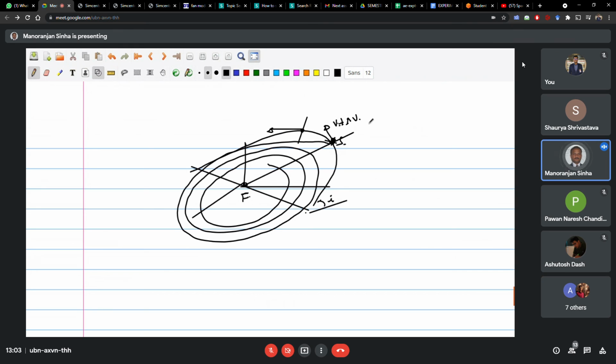So this will come once we do the trajectory transfer. At that time, many problems we will have. So for changing the argument of perigee, it's necessary that except at the perigee position, you give impulse somewhere else, and then the argument of perigee will change. Otherwise not. Here in this case, only a is decaying.